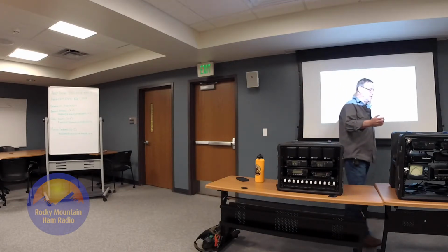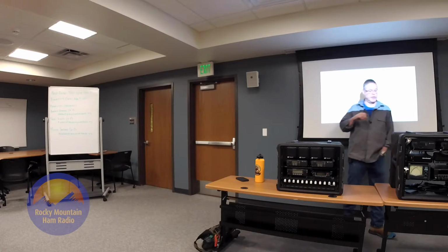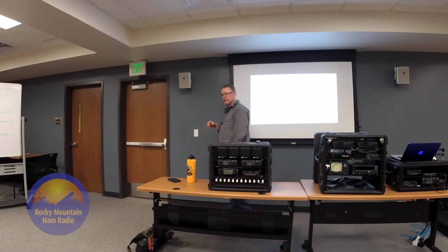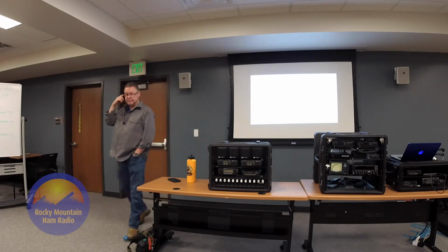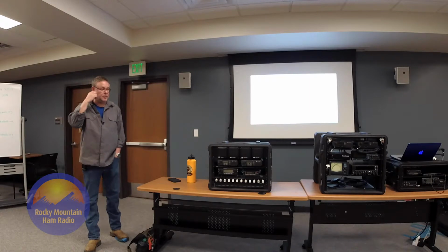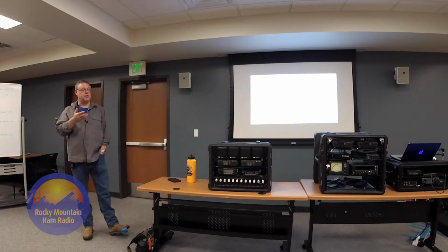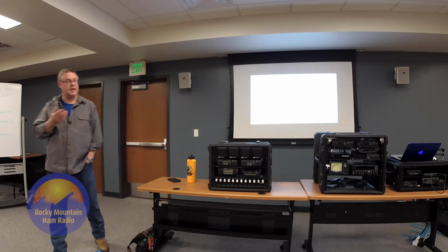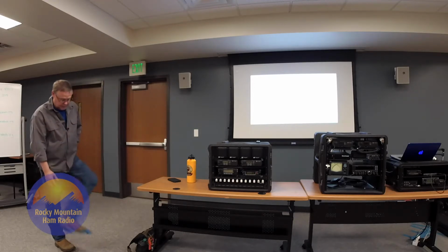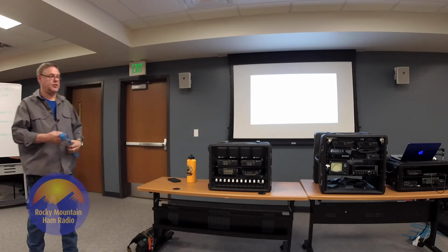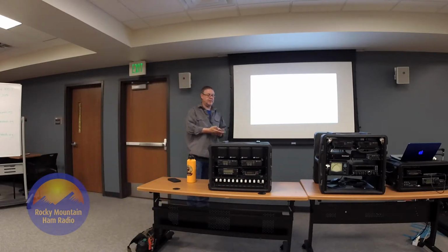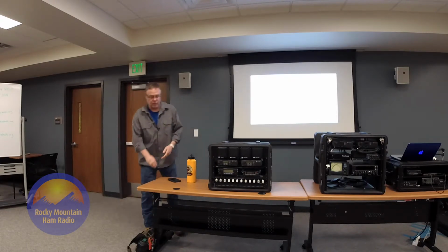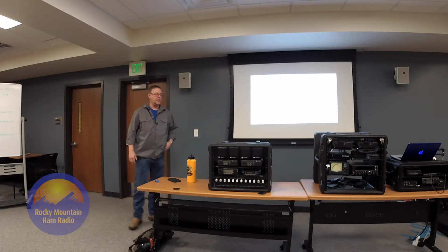100 watts, obviously, at 12 volts takes a lot more current than your 2-meter rig running 15 watts at 12 volts. Proper wire sizing. Keep in mind, typically you're going to be using no larger than 10 gauge in one of these things. Keep your wire length short if you can, which is a good practice for anything. Obviously, you're not running far inside of this, but it quickly becomes a rat's nest with all your interconnecting cables if you don't manage your wire runs.